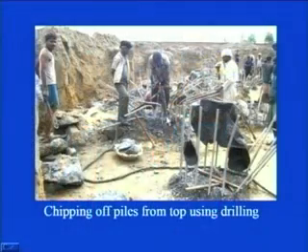It is not that only piles will be there. You have to provide a connection in all the piles such that the load from the superstructure will come to these and get distributed uniformly to all the piles and then to the subsequent soil strata. So, the reinforcement of the pile will go into the structure that will be coming just on top of the pile.